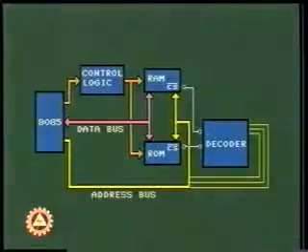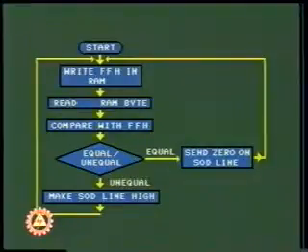Let us consider an example to describe this. Interfacing the microprocessor with read-only and read-write chips is one functional module. Now, we write a small program that does nothing but simply loops back after writing a byte in the RAM. We will read back the byte to verify whether the data bus is properly connected or not. The result is displayed on the serial output data line SOD.